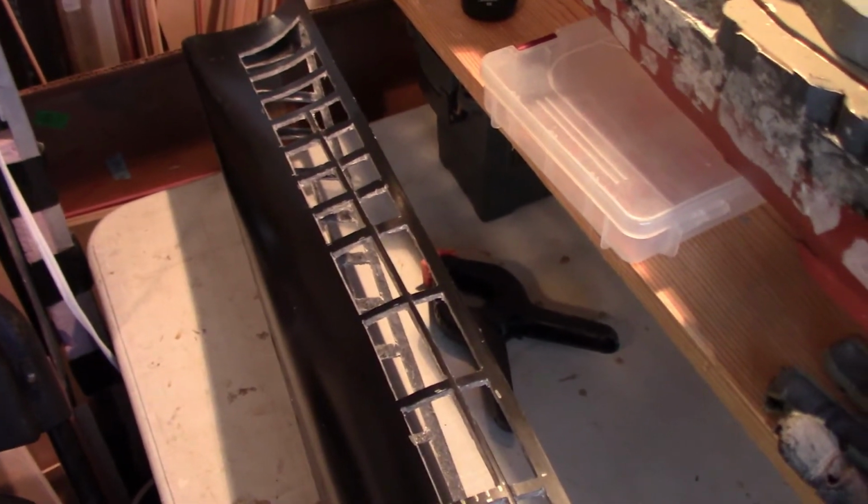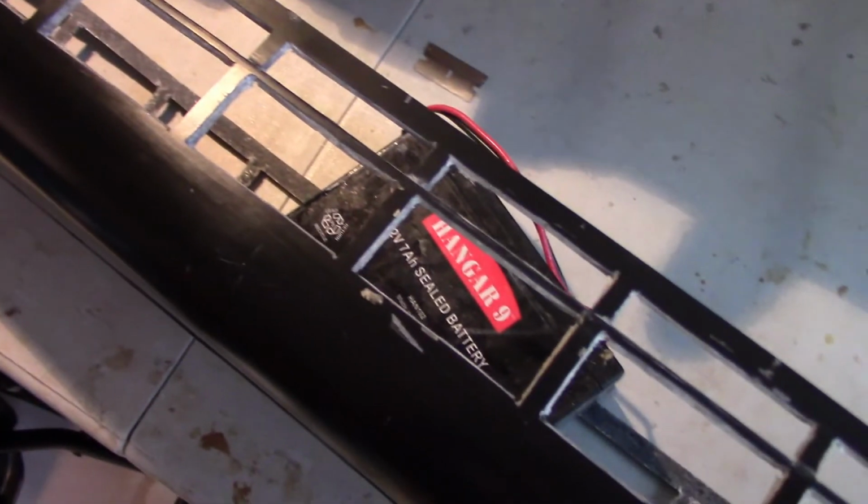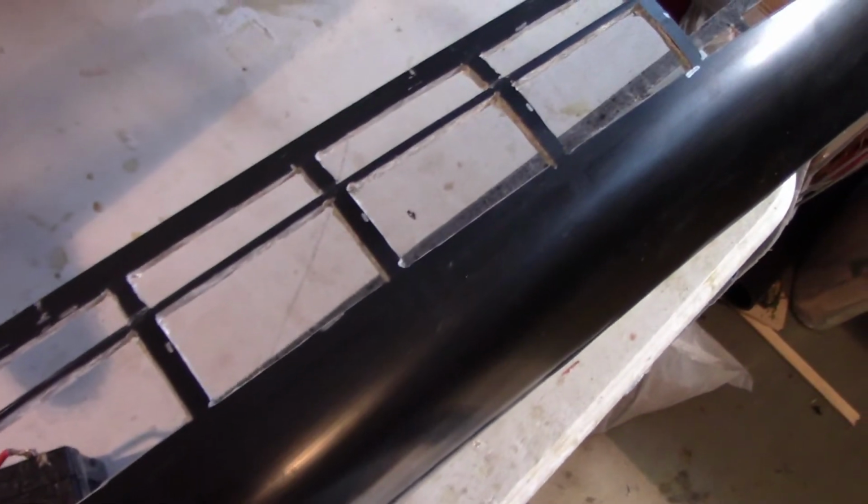If you know off the bat before you cut it out that the rib thickness isn't good, you might want to add more fiberglass to the inside before you cut it out, because then you only cut it out once. But a lot of times the hull might look thick, and then when you go to cut through it, you realize that there are some thin areas, so you've got to reinforce them.